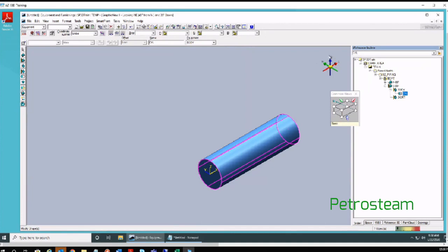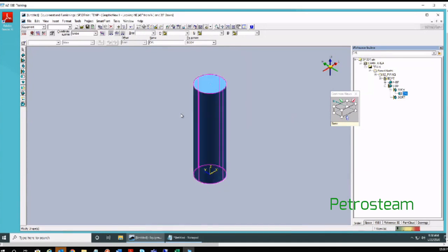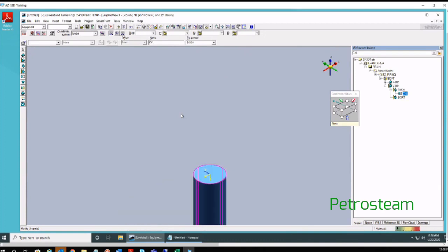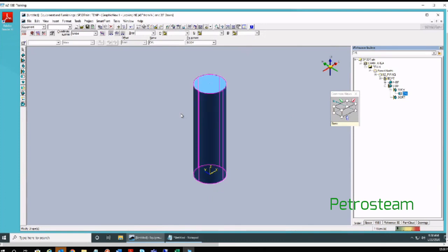Correct? So based on your 3D concepts, you have to activate the axis around which you have to rotate by using the up arrow mark. Once the required axis is active, use the right arrow mark to rotate it by 90 degrees. If it is not the place, use the up arrow mark multiple times to bring it to the required position.